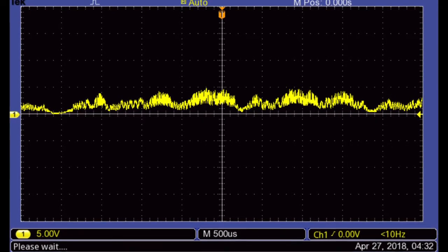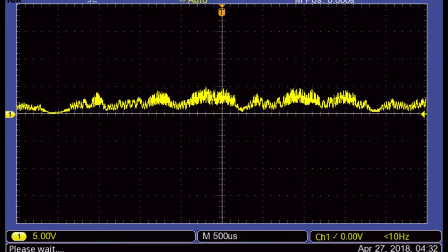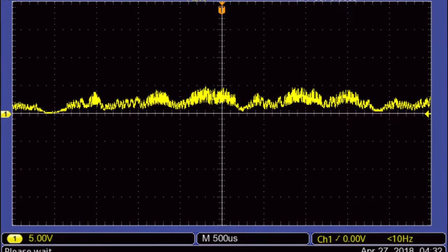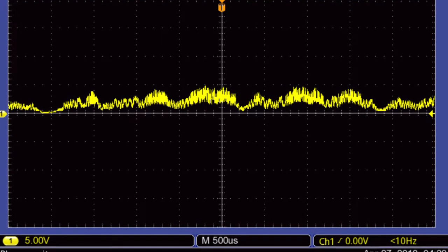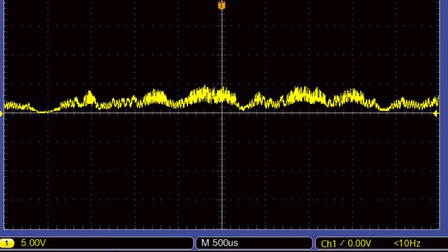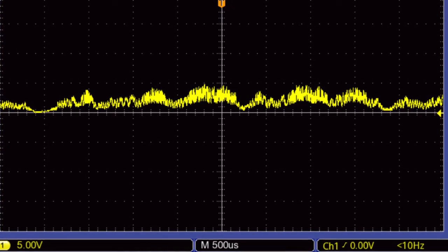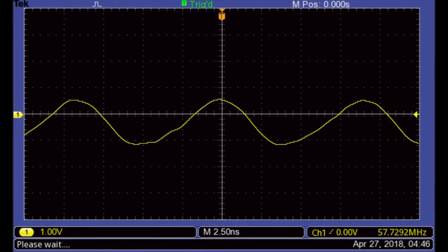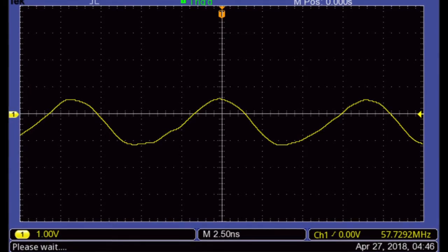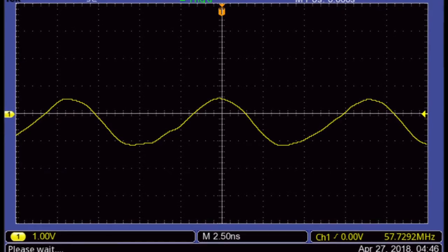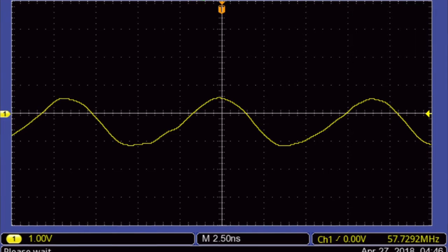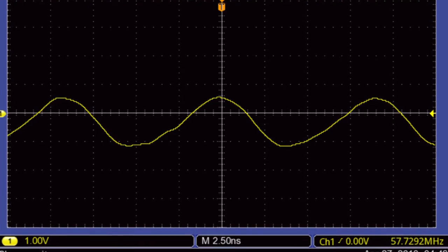This is a screenshot of the potential measured at the output of the antenna of the transmitter. Here, the frequency modulation can be seen as the wave's period shortens and lengthens. Now, let's zoom in. Unfortunately, this doesn't tell us much because this is above the range of the oscilloscope, so we have to use the specialized spectrum analyzer.